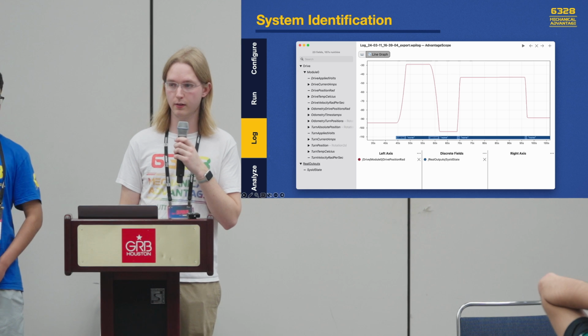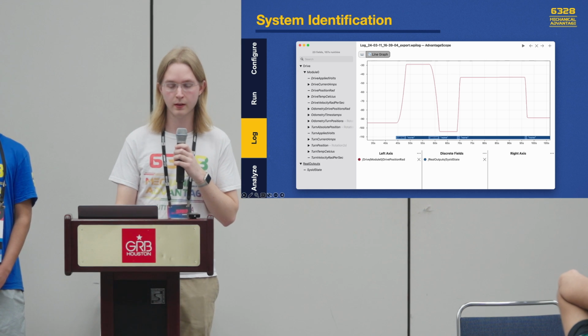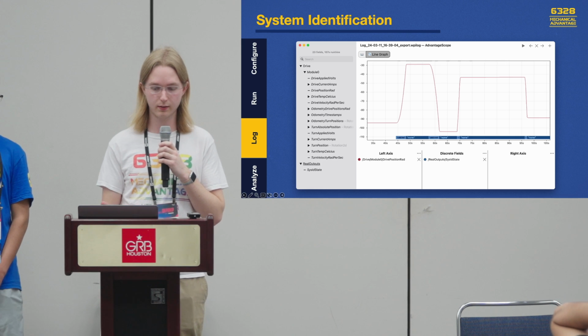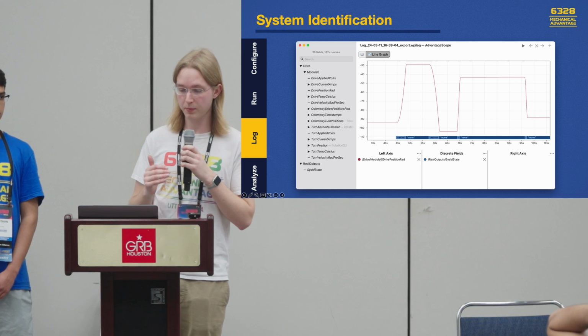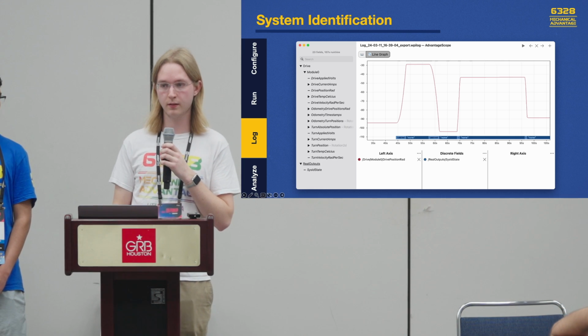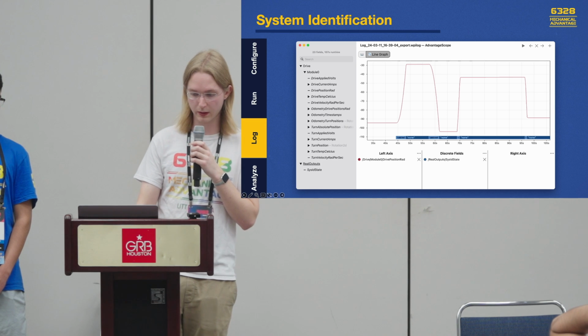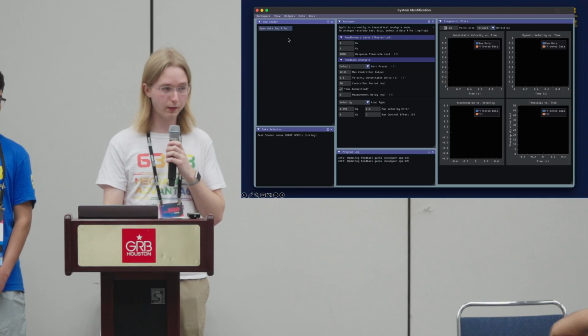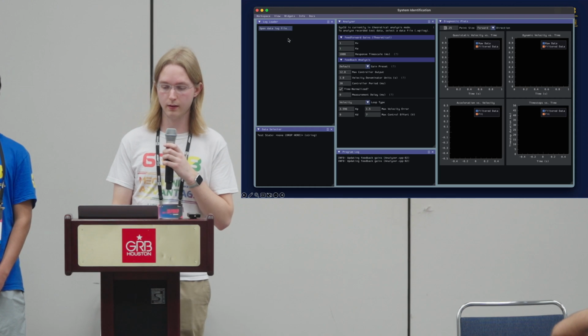So here you can see along the bottom is our test state, and then we're showing the position of a swerve module over time during the test. It slowly ramps up during the 2 quasi-static tests, and you can see it accelerates much more quickly during the latter dynamic tests. And the final step is to actually calculate those gains.